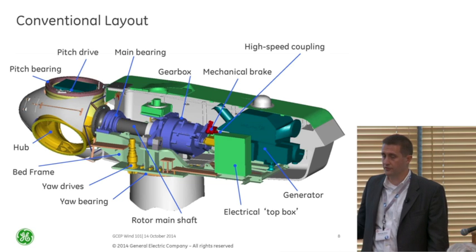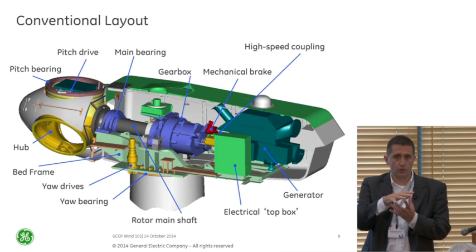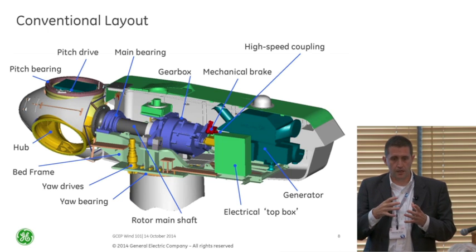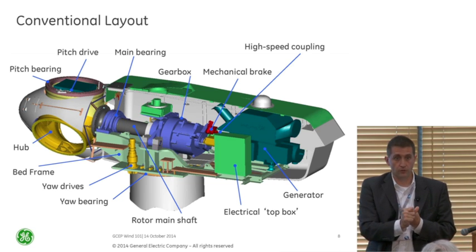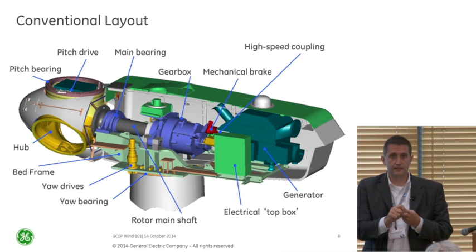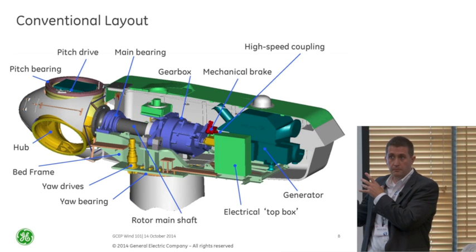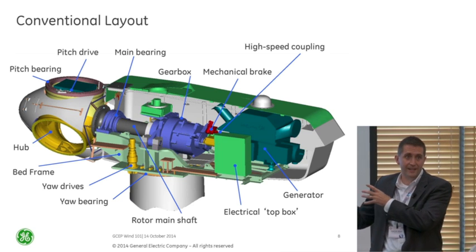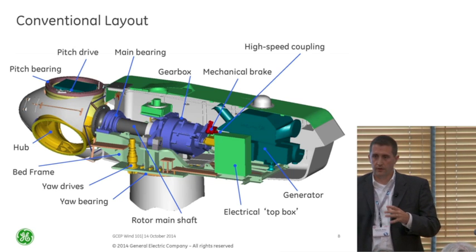There's a lot of other pieces here that are really important as well, especially when you add up the cost, right? There's a lot of structural pieces: the hub, the bed plate, which the whole drivetrain is going to sit on, the tower. Those are really expensive pieces that are really just structural pieces. So how do you handle loads and controls to minimize the loads those things have to maintain, to make them low cost? And then also, how do you do mechanical design well enough that you can really reduce some of the costs of those components?